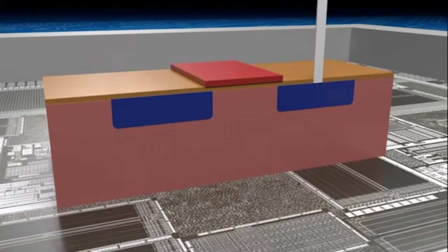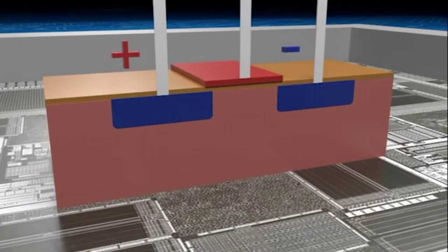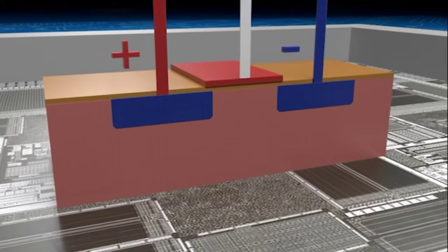Every transistor has 3 terminals. The middle one is attached to the gate, which is the electrically conductive polysilicon. If an electrical charge is applied to only the 2 outer terminals, electricity cannot flow as the transistor is blocked. This changes, however, if an additional charge is applied to the middle terminal. Electrons from the p layer are then pulled toward the middle terminal and accumulate at the area bordering the silicon crystal and the insulating gate oxide.